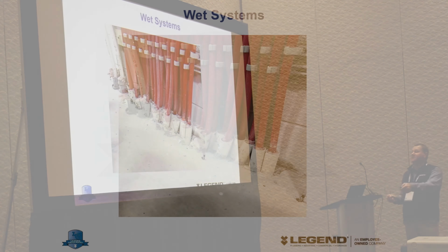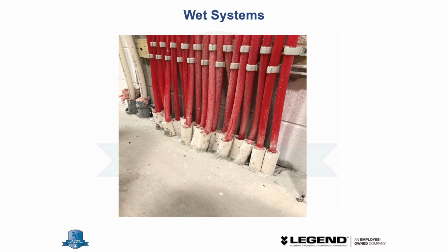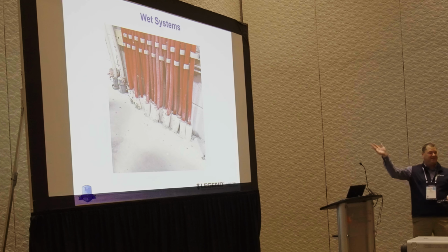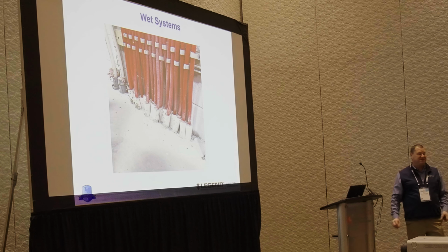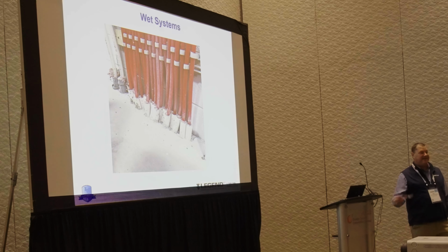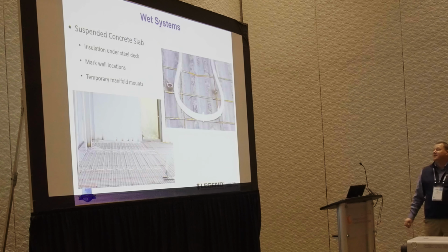This contractor did a great job. He also put insulation in each one of those things, which is a great best practice. And the only reason for that is, if you've ever seen them pour cement with the wheelbarrows, and they're just running around doing this, if they do that onto your nicely installed tubing with two protection sleeves, and the cement goes into those two protection sleeves, you don't have two protection sleeves anymore. You just got a sleeve around some more stuff. So, not a bad idea. I never saw that before until I saw this contractor do it. I'm like, that guy's got burned before, and he's adapted to the new best practice. So, good thing to think about.